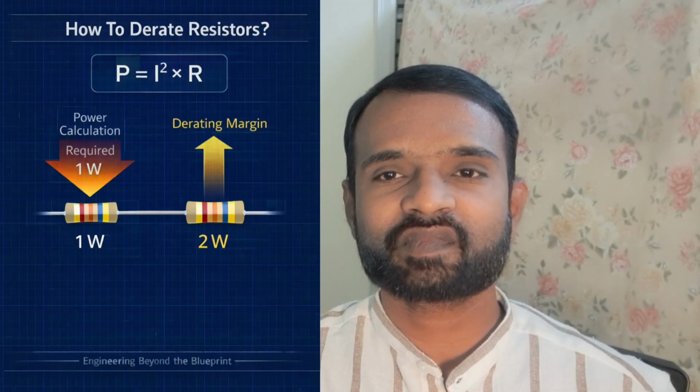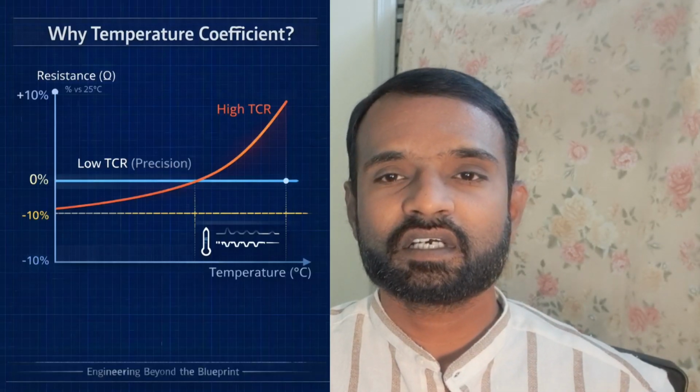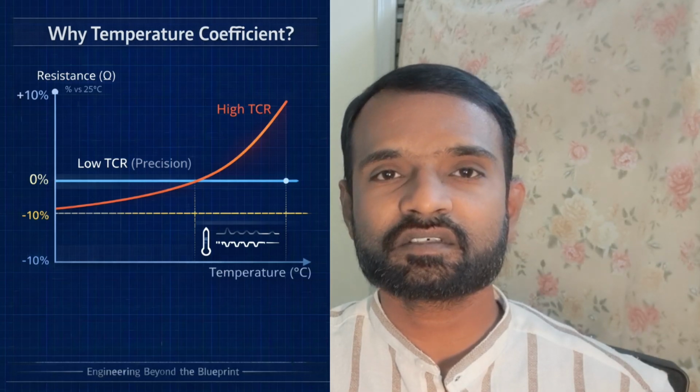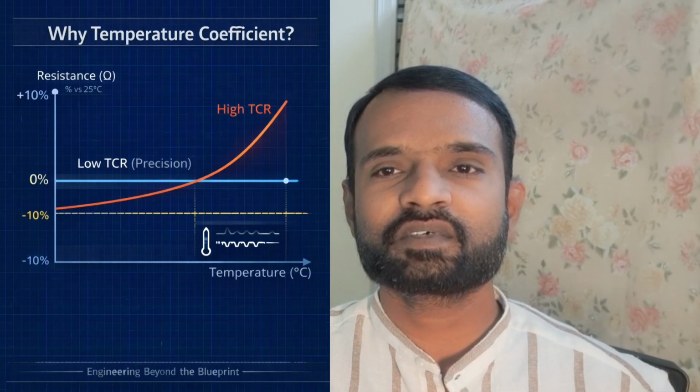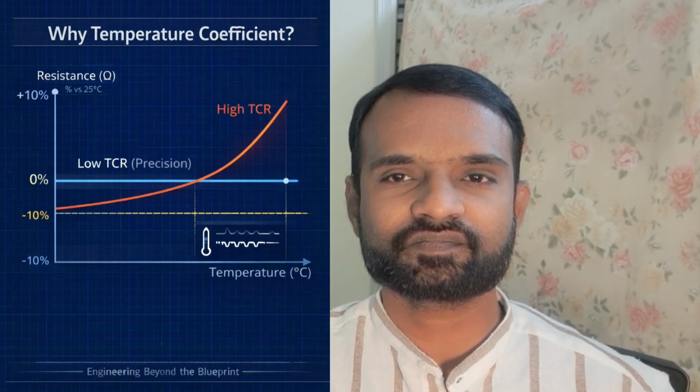as a resistor. What is a TCR? It's nothing but temperature coefficient of resistance. If anything changes in the resistance with the temperature, right? So that is how we are going to measure the TCR. For example, precision ADC circuit needs low TCR resistors.